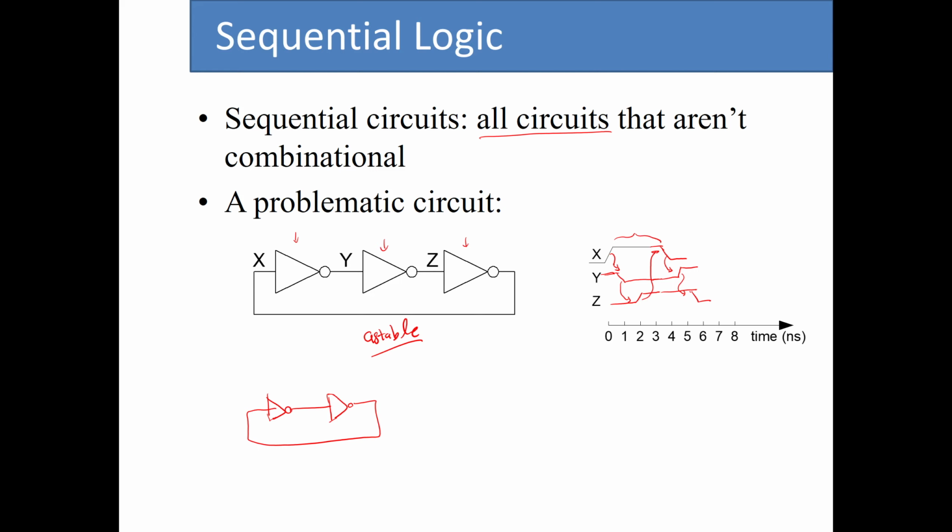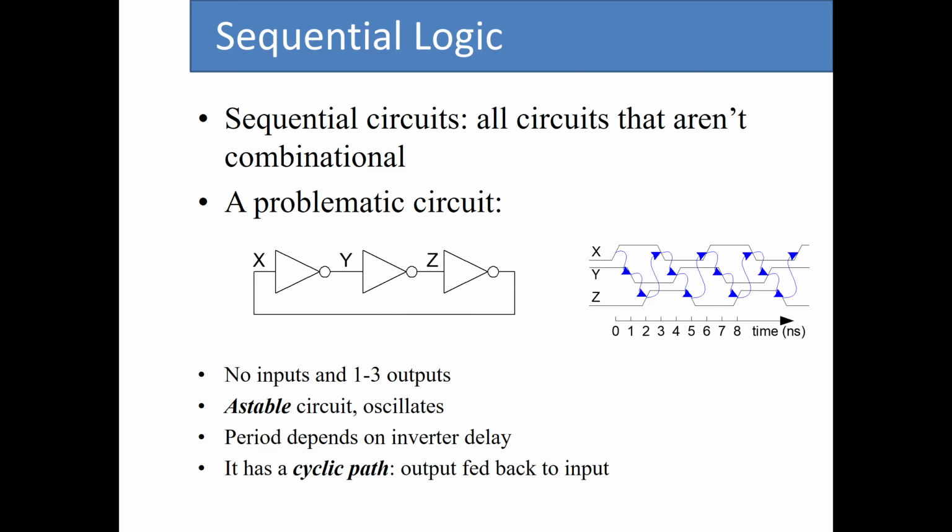You remember from before, when we talked about the timing of the combinational circuit, we said that there is a minimum and a maximum for the delay of any individual gate, and we usually don't have control over the exact amount of delay. What we know is basically a range. So because of that, controlling such a circuit is very hard.